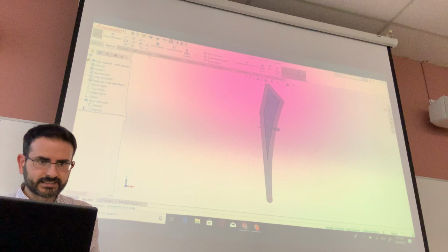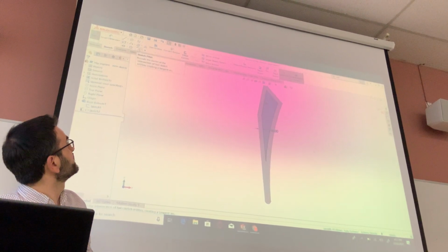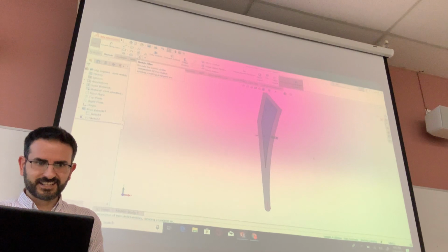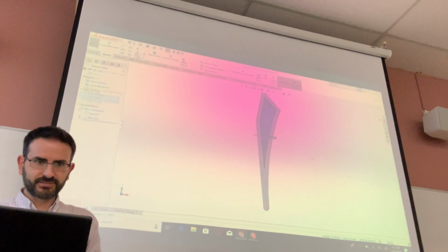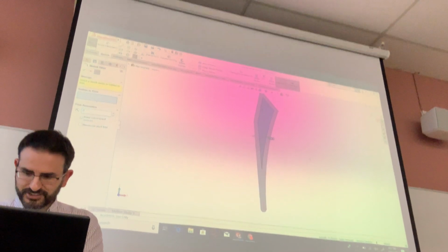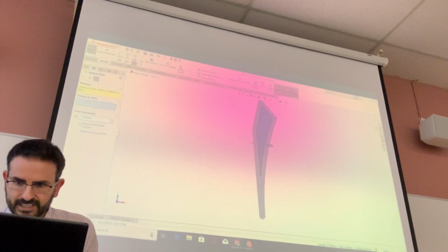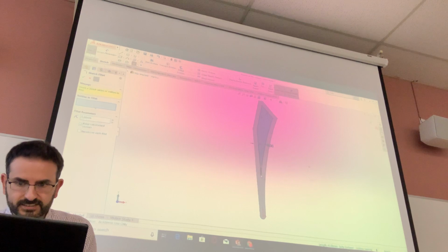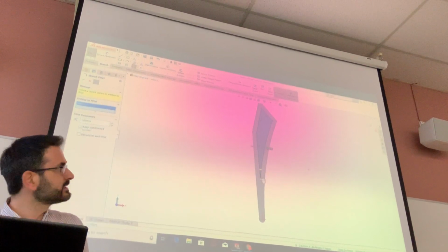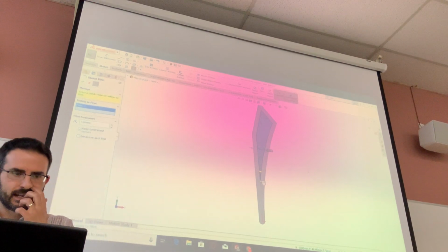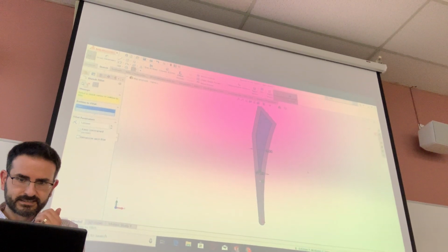And so what I'm doing is that I'm creating a fillet, or a filet, if you're French. So create a fillet, the first one is going to be 1 millimeter radius, and it's going to be this tiny little corner at the bottom. And you see that when you select it, it shows you a preview of what it's going to look like. I like it, okay.